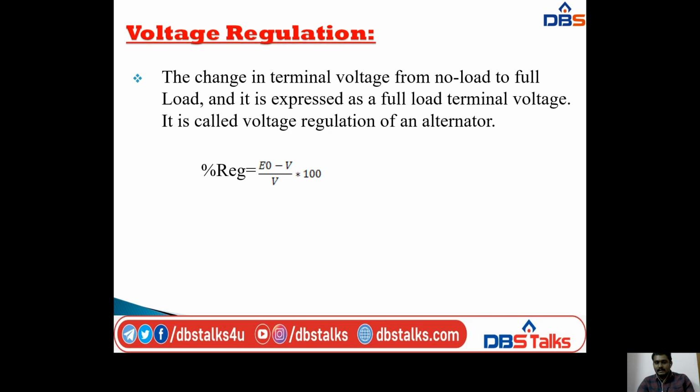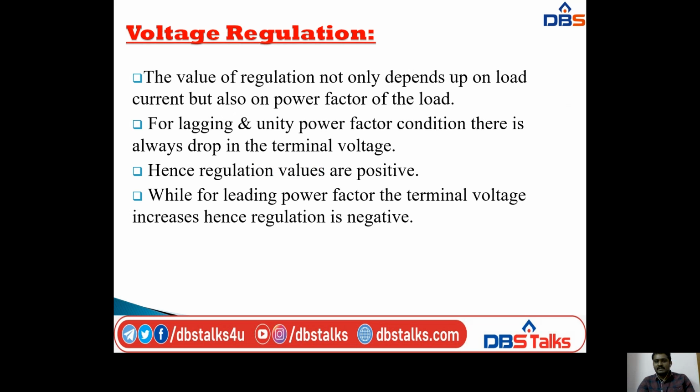So here I am writing this as the equation: percentage of regulation is equal to (E0 minus V) by V into 100. Here E0 is the no load voltage and V is the full load voltage. So the difference between the no load voltage and the full load voltage, divided by the full load voltage, into 100 is known as the percentage of voltage regulation.